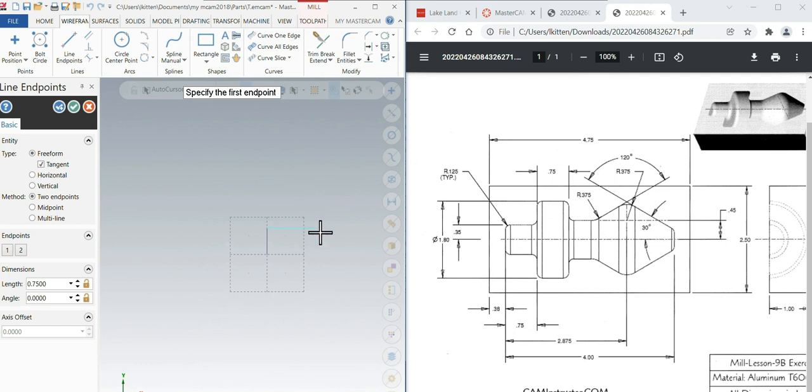All right, now we're going to pick on the end again, so we're going to keep on doing this. Okay, now this one gets a little trickier. This one says you have to either do the math in your head or let MasterCAM do the math. I'm going to show you how to let MasterCAM do it, so it's not so hard. We're still at 0.75 over. We haven't gone any left yet, but we're going to go half of 1.8 high, so 0.9. So type in spacebar and 0.75, because that's where we're at right now, comma 0.9. Okay.